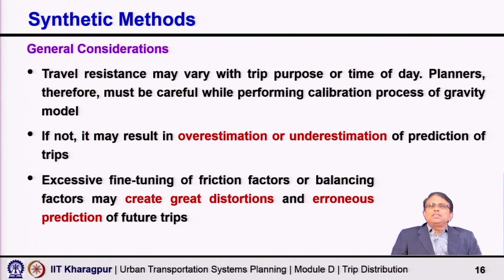So, remember that we are doing this for planning purposes. There will always be some error in model estimation, some error in data collection, anything. The whole modeling work cannot go without error. All we need to ensure is that our error is not too much, right. That is why we want gross level matching. But as I said, even with the zone to zone adjustment factor or socioeconomic adjustment factor, beyond the trip length frequency distribution, why are the individual cells not matching? Because of the socioeconomic composition.